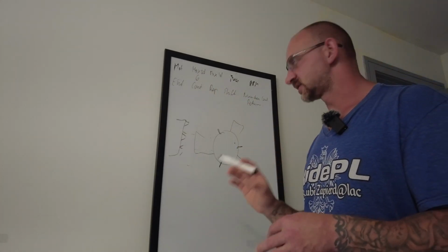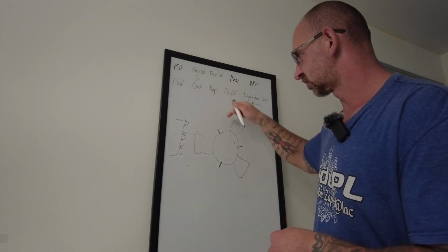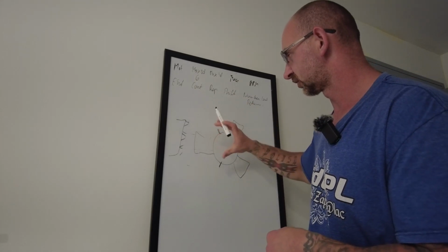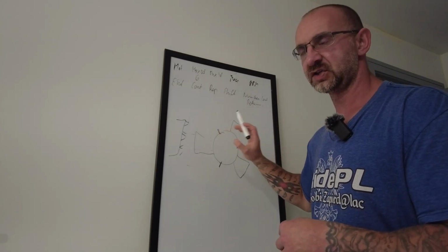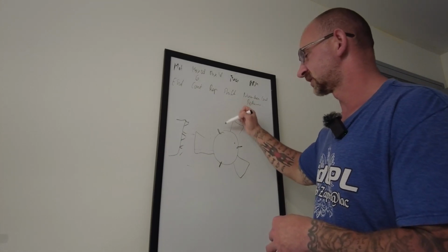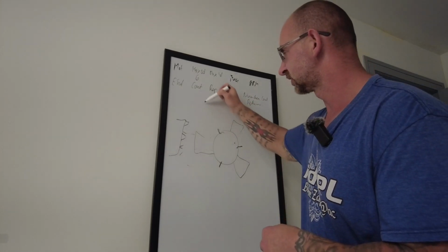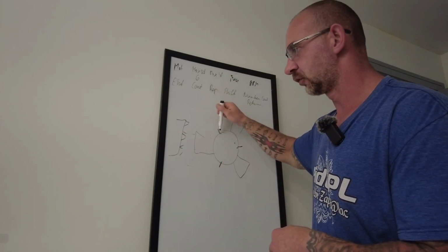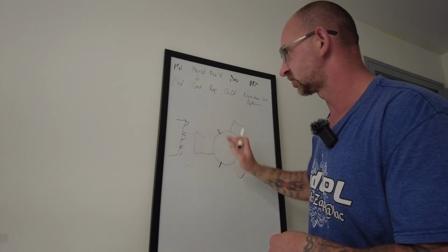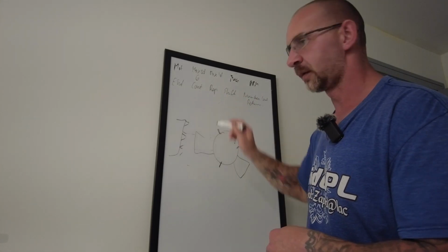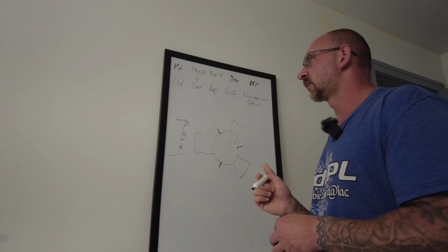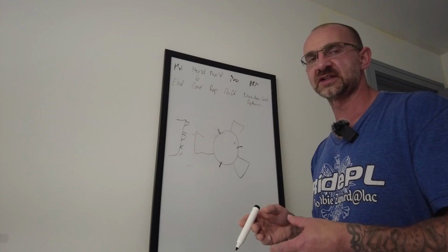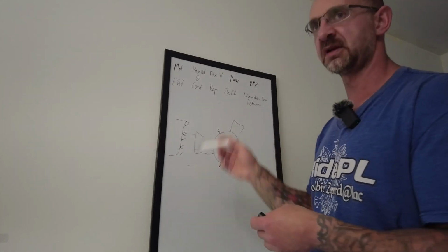So there, for clearance sometimes, for example, if you're going right in between the jaws, if you only retract a little bit, and then you have that jaw rotation, and it's gonna hit your holder. If you tell her your material is, for example, 8 or 10 inches, it will retract far enough to where it rotates, and then you come back and you go between jaws, right? You finish this feature, you go up, it rotates, then you come up. So this is why setting up the material size is important. So technically you use it for clearance moves, tailstock, milling, and other things.